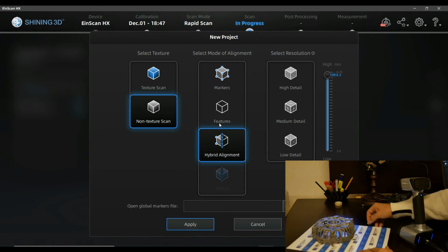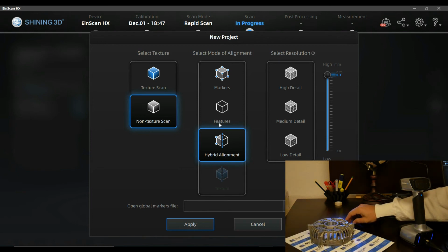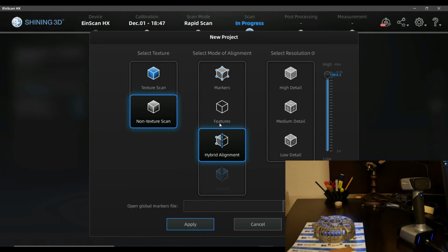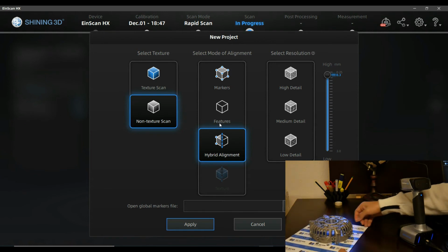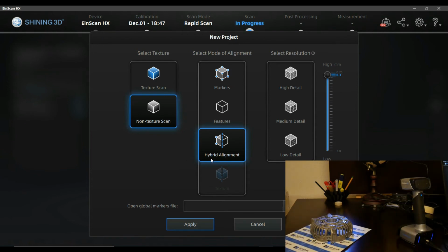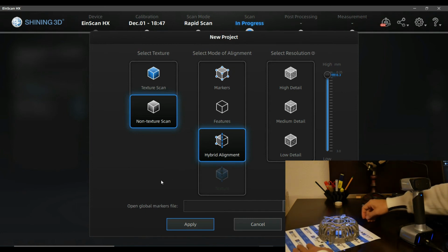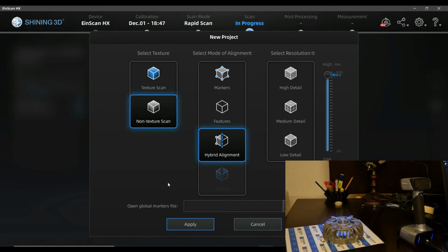As I was creating the environment markers in the laser scan, here at the end for the side view, I see that they are not enough for this flat view where I'm looking, for example, from upside or downside. It's important that you always see enough markers. So I'm going to put some additional ones there right now.